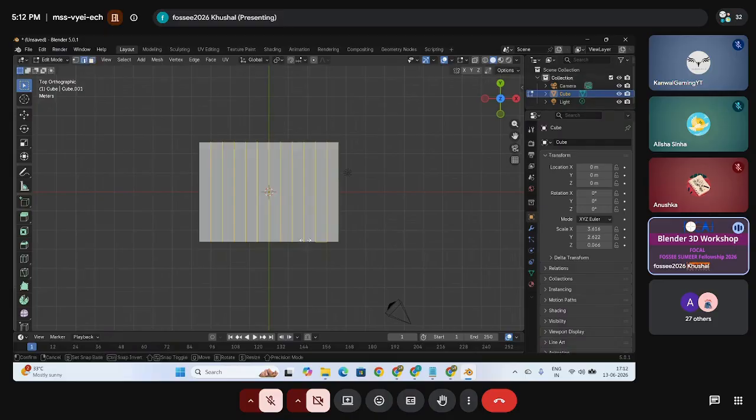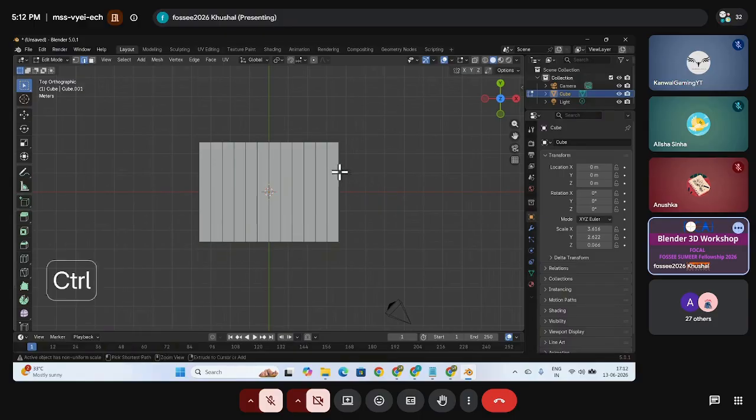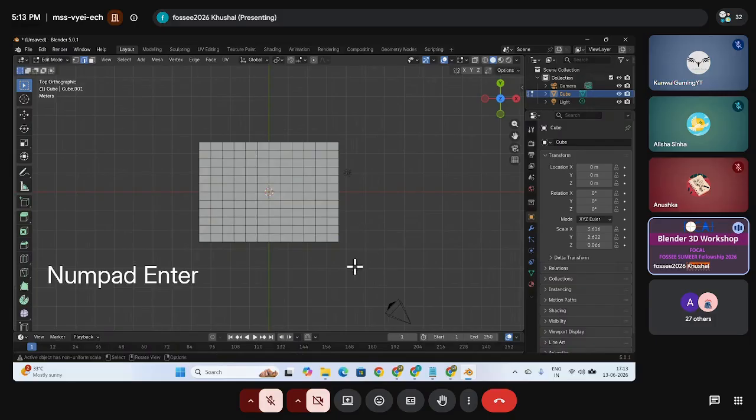Yes, this much, okay, and click, click, done. Now I want horizontal loop cuts. So I will click it here. I will press Control R here. See, the horizontal loop cut is created. Click and click, done. So this many loop cuts are created on the face.